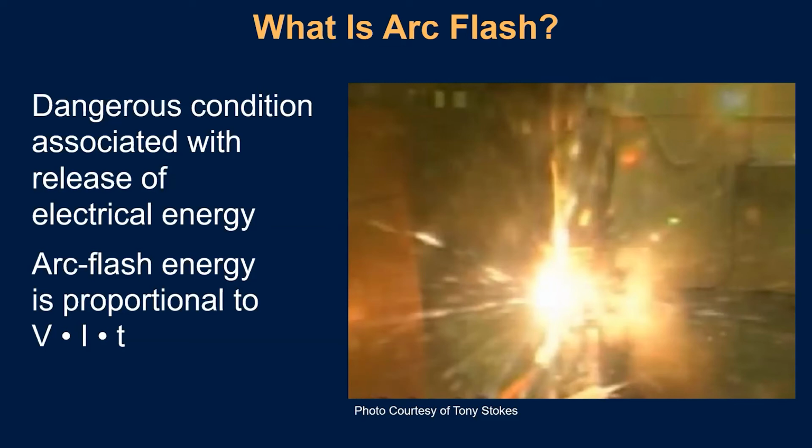Talking about arc flash, the blast that occurs with it because of the expansion of air, called the arc blast, is also a phenomenon that accompanies that arc flash. And then there's another term called the arc flash incident energy, which is the energy at that working distance, and you typically measure that in calories per centimeter square, or in joules, or equivalent joules per centimeter square. Looking at the units, you can see that the closer you are to the source of this arc flash, the energy that's incident on that surface increases quadratically.